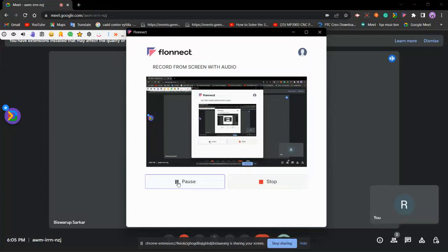No, that is because while defining this, I selected this thing. That dimension is already fixed, already known, because from here it is 55, here it is 40. And the software thought that I was going to give a dimension for this one, but actually I was going to select these two and give the dimension for this one. Okay, the dimensioning is done. I'm giving exit workbench, and currently I'm out of the workbench.